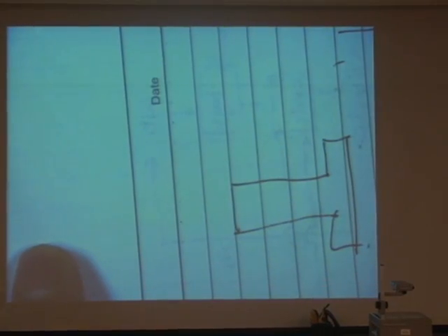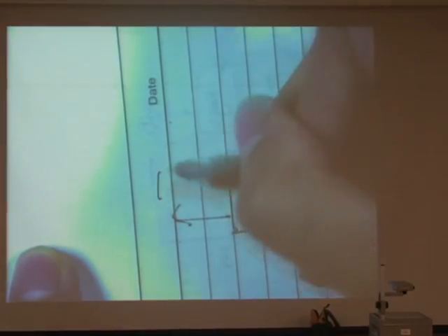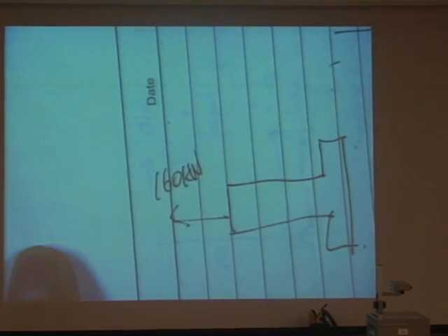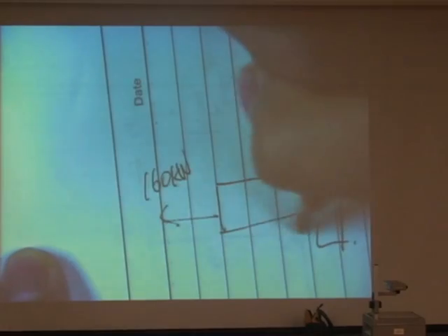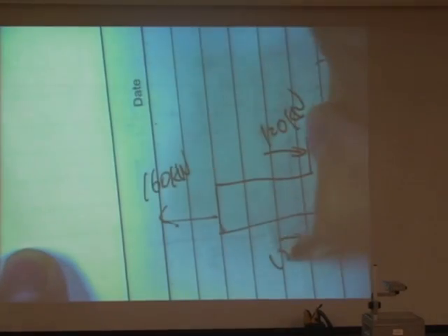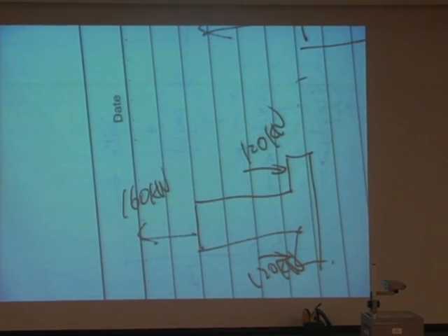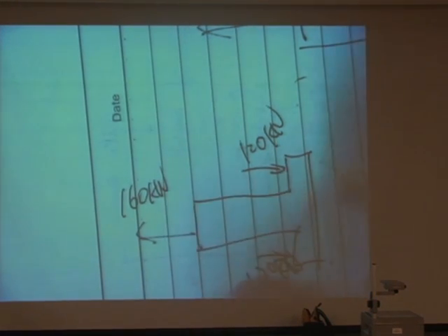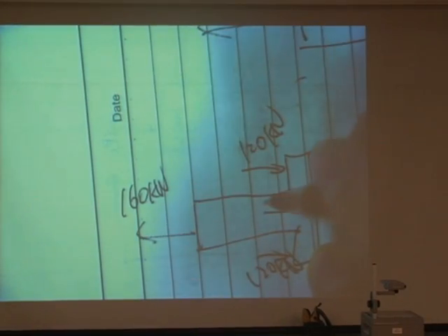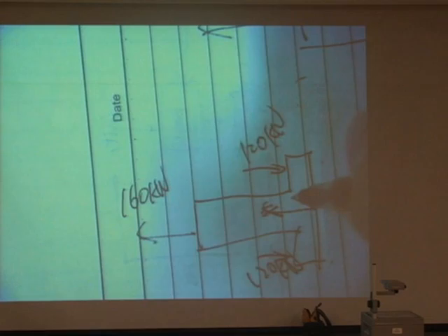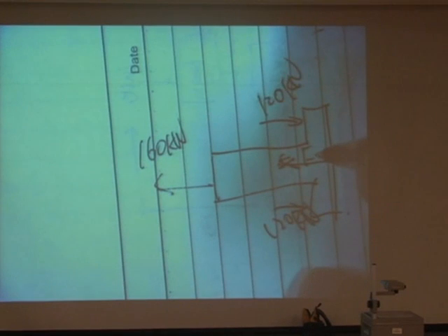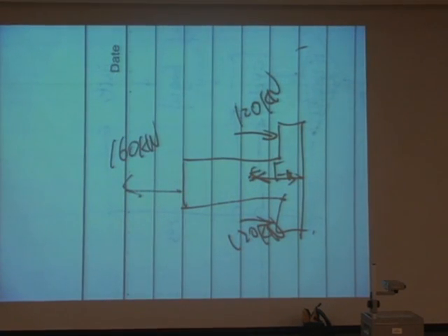What are the forces experienced by this AB? First, definitely the most obvious one is the 160 kilonewton, correct? Then 120 kilonewton from both sides. Are there any other possible forces acting on this part? Yes, the force acted by the second member on this one. What is the magnitude? Currently we don't know. This is from the member BC. We call it FB. So these are the four forces experienced.